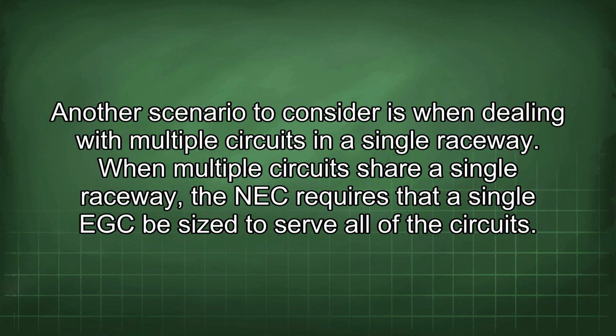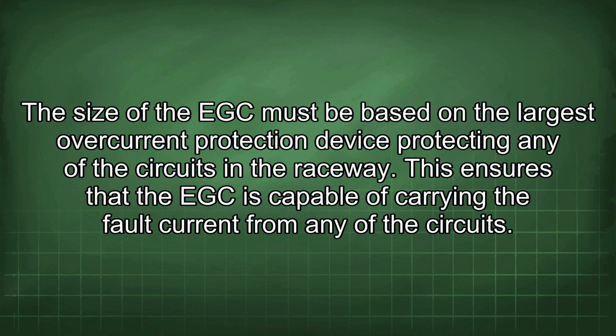Another scenario to consider is when dealing with multiple circuits in a single raceway. When multiple circuits share a single raceway, the NEC requires that a single EGC be sized to serve all of the circuits. The size of the EGC must be based on the largest overcurrent protection device protecting any of the circuits in the raceway. This ensures that the EGC is capable of carrying the fault current from any of the